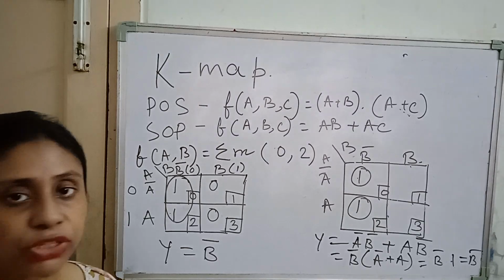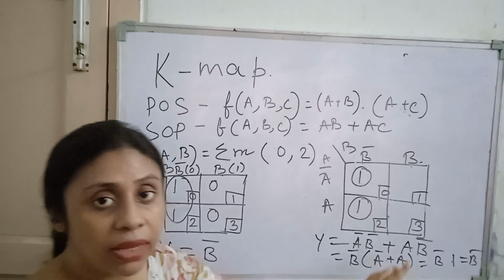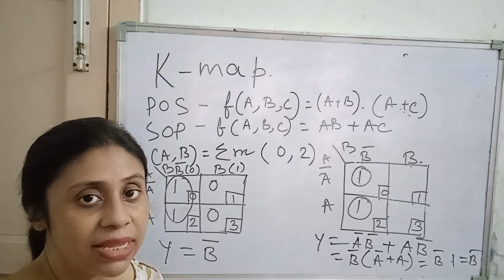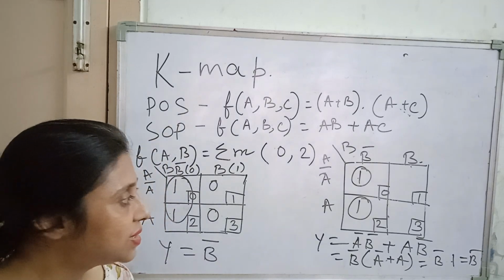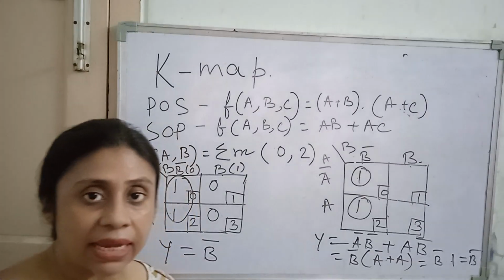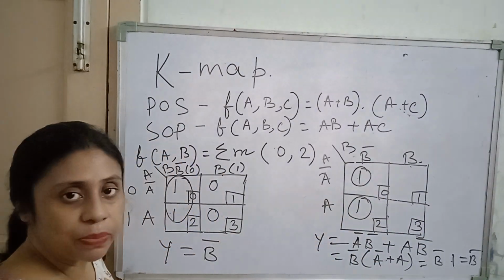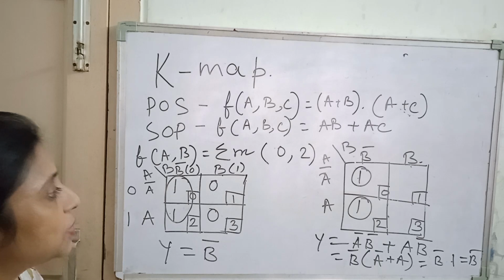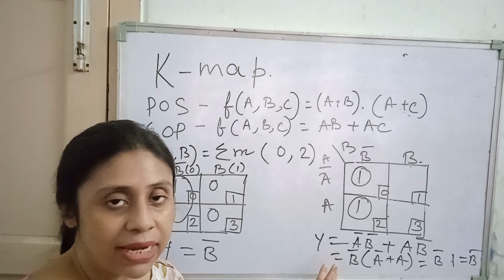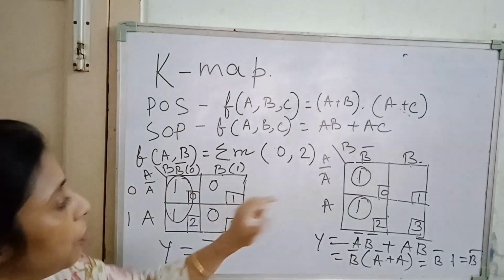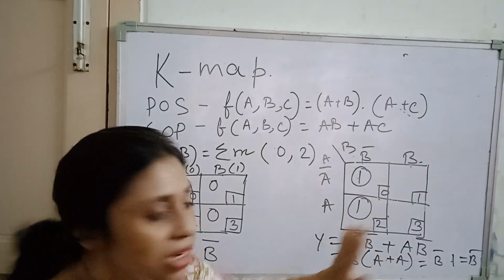So these are the very basics of Kmap. And one thing is very important, while you are putting box numbers, keep one thing in mind, that is which one is your MSB and which one is your LSB, because accordingly the box number will change. How the box number will change? See, A is our MSB for this particular example. That is why we are writing like A bar B bar. A we are putting first in the left side. So A is our MSB. We are putting our MSB in rows, right? And these are our box numbers coming.